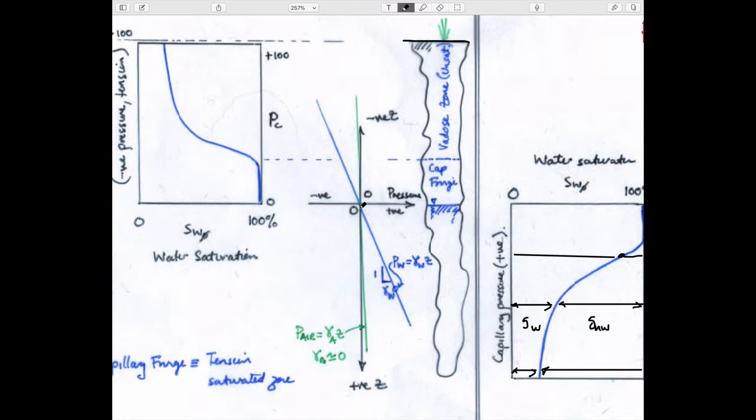If you drained out the water and looked at air-filled pores, the pressure in the air would increase as you go down, just because of the height of water above it. Same as the fact that we're at 14.7 psi here, and if you go up to the edge of the atmosphere, you're at 0 absolute pressure. 1.01 bar, 100 kPa absolute pressure at sea level, because of all the gas that sits above us. And so as you go across this boundary, there's no reason why the pressure changes shouldn't just keep on going up.